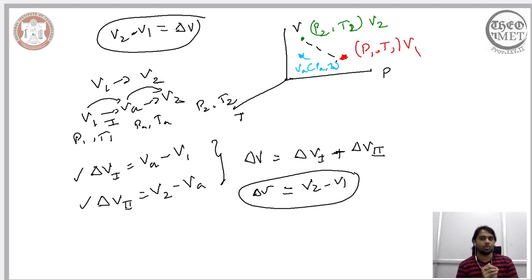So this again substantiates our definition of the state variable. Irrespective of the number of detours you take, irrespective of the number of intermediate steps you take, when you have an initial state and a final state, the difference in the state of the system, particularly when it is described exclusively by state variables, is nothing but the difference between the initial state and the final state. This is one of the characteristic features of defining a state of the system using state variables alone.